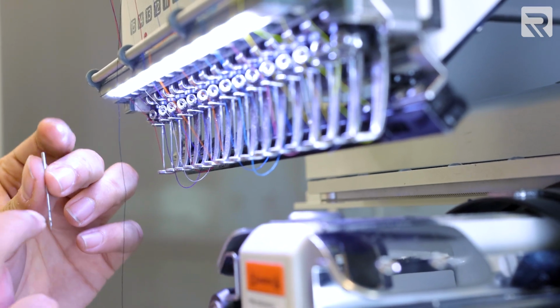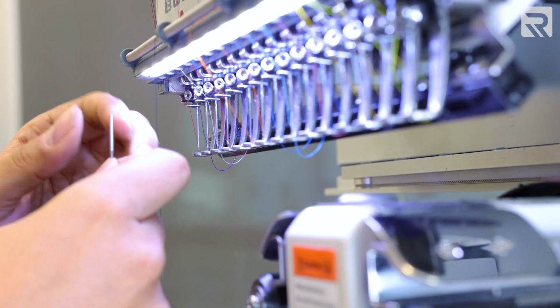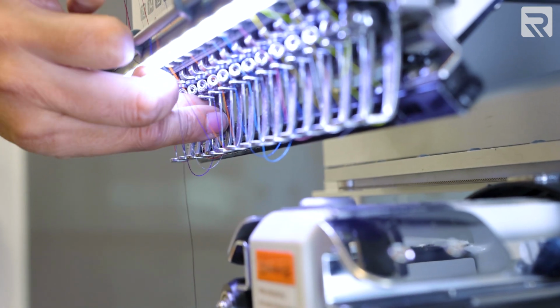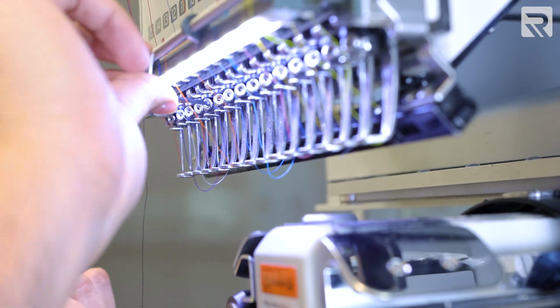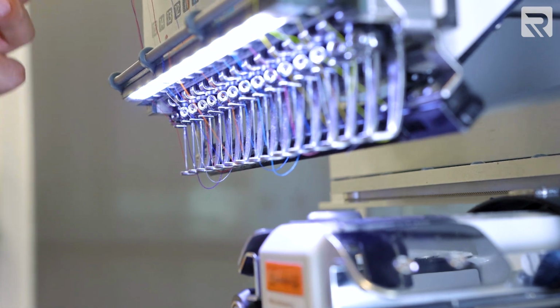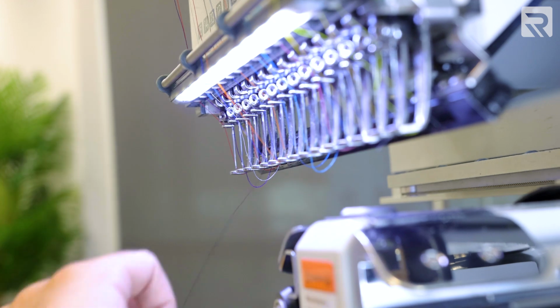We wanna make sure that the scarf of the needle points back of the machine. Put that right here. Let's bring this up right here. Let's go ahead and tighten. All right, just like that. And we'll go ahead and rethread our needle. The reason we're changing our needle is we're working with thick material, so we want to be able to go through the material without shredding it.